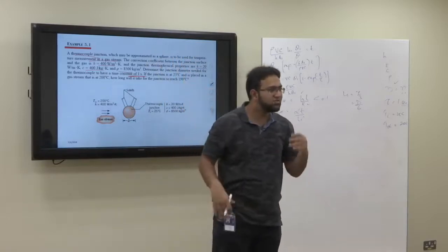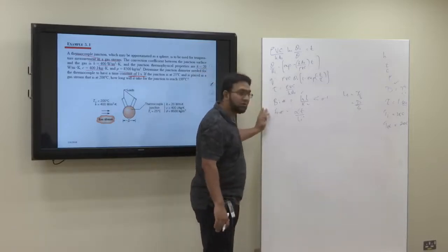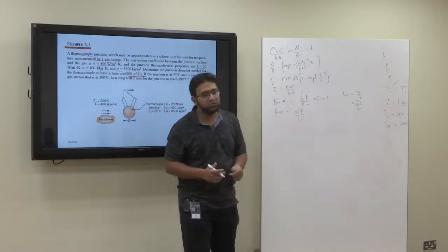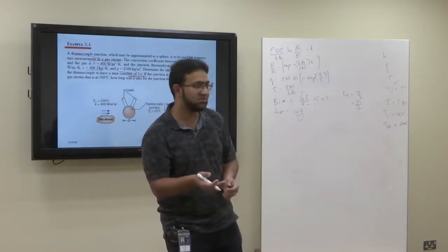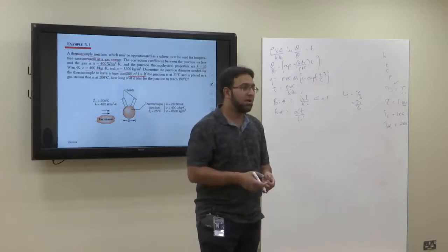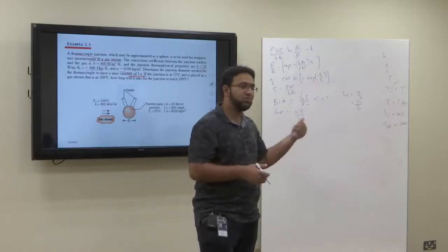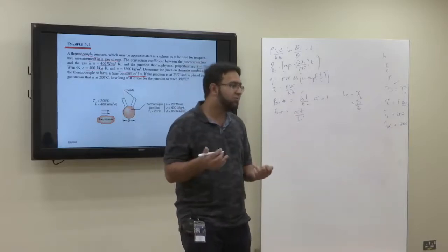Okay? So let's assume that, because all these formulas that you have seen written here are applicable only for the case of lumped capacitance analysis, if that approximation is applicable. For that we need to know the Biot number, but we don't know the Biot number because we don't know the diameter. So we cannot proceed in any case.